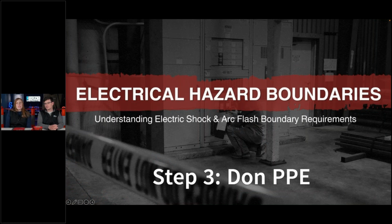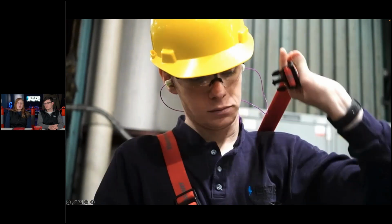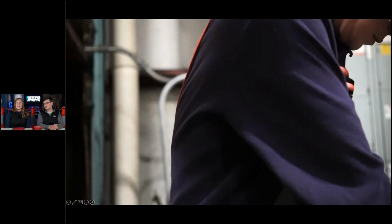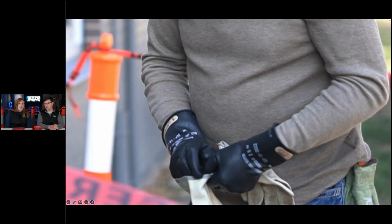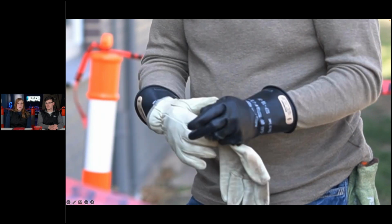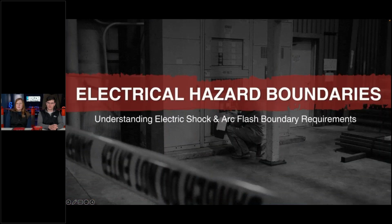And then if you're going to be in those boundaries, you got to make sure you have the right PPE. Okay, so don whatever is needed prior to entering and opening up that equipment. Okay, so putting on the suits, making sure you got those bibs on or graded uniforms or coveralls, whatever you've got, safety glasses, hearing protection, and maybe you got the full 40 cal suit jacket as well. Certainly your gloves, you're really not going to get away from those either. Okay, your rubber gloves with the protectors over the top of them, making sure you inspect and make sure everything's in good condition, and field testing your gloves before putting them on.